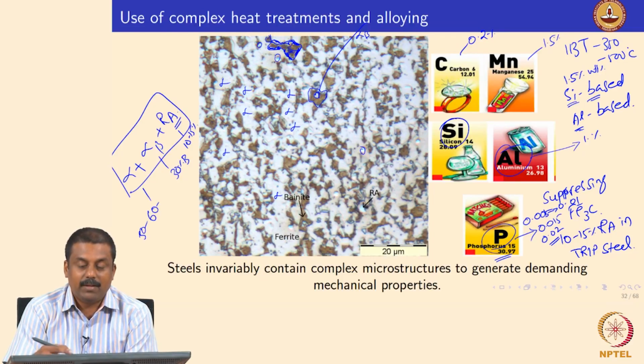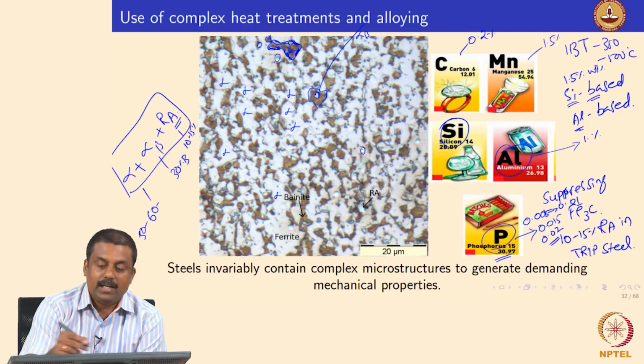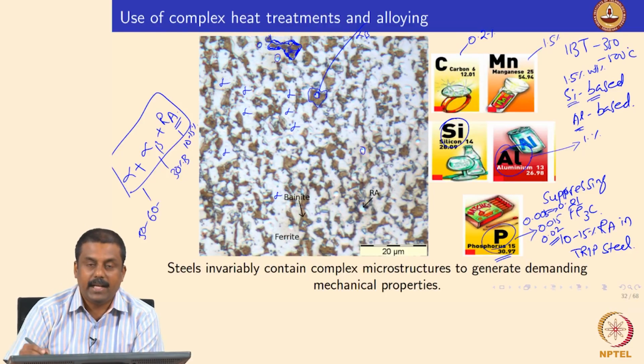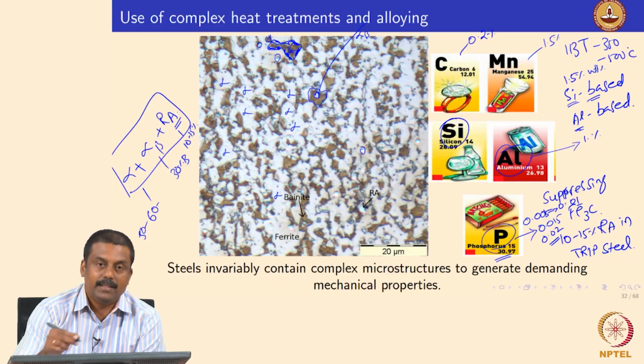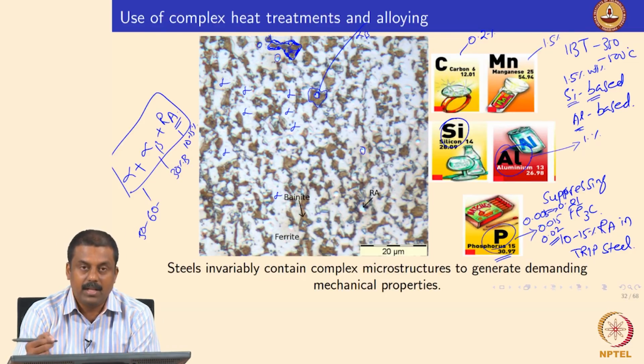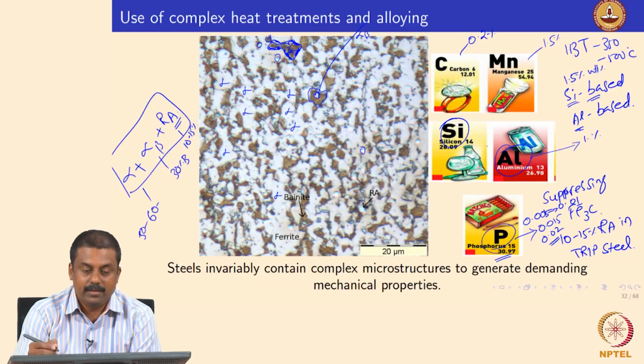So we need to understand how these alloying elements behave, how they segregate, partition and migrate during solidification and subsequent phase transformations while applying a weld thermal cycle. From that understanding, we can develop thermal cycles that are suitable for welding these steels, TRIP steels and dual phase steels.